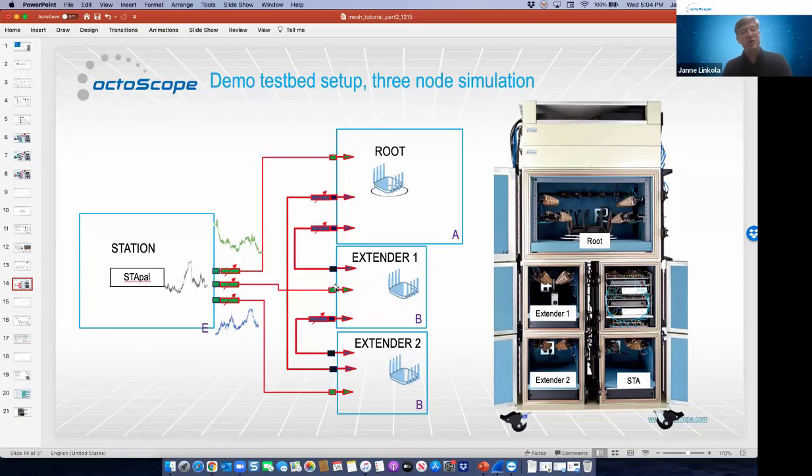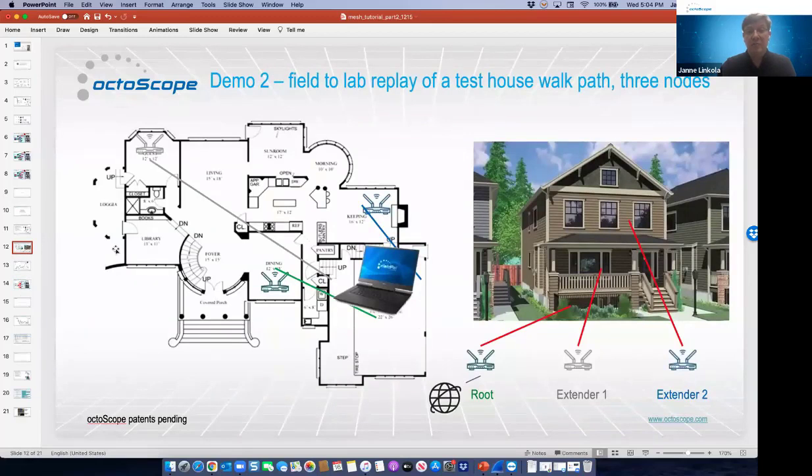Right now, you could say, well, maybe there's a mesh technology that has particularly powerful radios, and it would really be advantageous to locate them slightly differently. There is no practical node limit when we perform this type of recording. We could have more than 3 locations captured when we perform this path loss measurement.